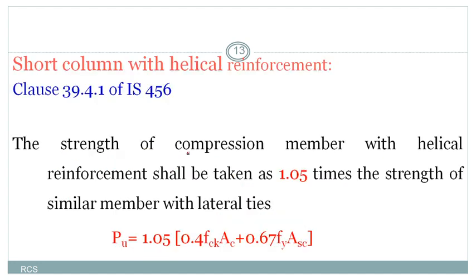Then for the same short column, if it is provided with helical reinforcement, the ultimate load that we calculated in the previous case should be multiplied by 1.05.